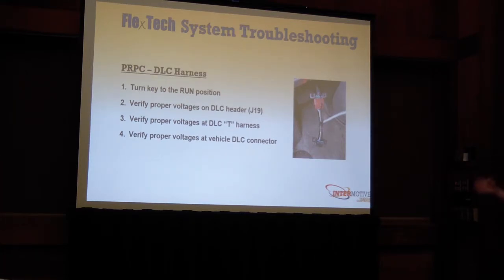So you can run down to the T harness, down to the OBD2 connector, check that, then move to the actual OBD2 connector itself, and verify the voltages there. It's possible that the fuse to the data link connector could be blown as well.